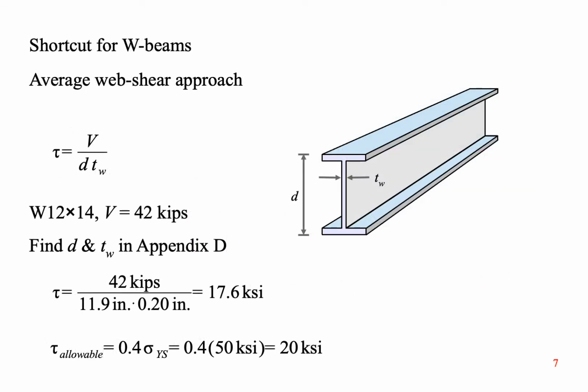The general shear formula is really useful for simple shapes, but it's a mess for complicated shapes because of the need to find y bar. Wide flange beams have complicated cross sections. We draw them as if they're made of perfect rectangles stacked together, but they are hot-rolled steel shapes with internal and external radii. It's easy to find A prime because it's just half the cross-sectional area A. However, finding y bar is tricky. You would have to find the centroid of the T-shaped A prime area, and that would be time-consuming.